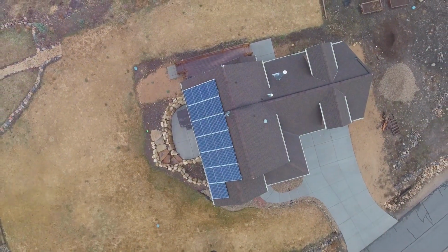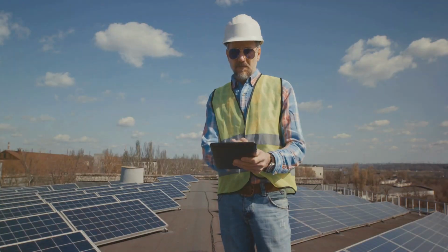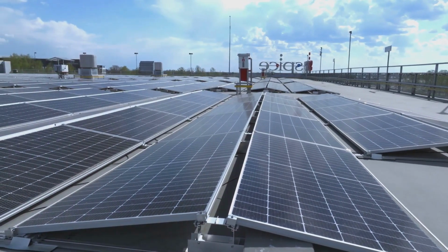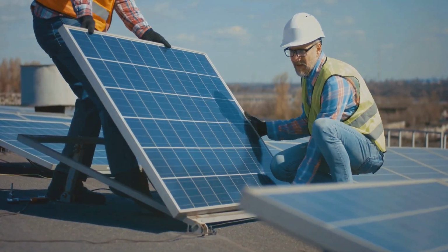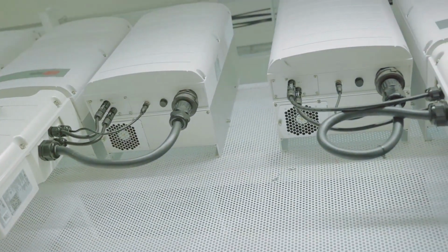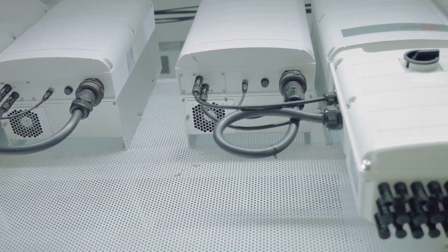To make the best choice, start by assessing your property and identifying any potential shading issues. If shading is only minor, high-efficiency panels or basic optimizers might work well. For areas with more complex shading, you might benefit from microinverters or power optimizers.